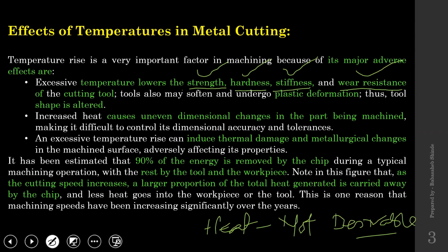But when there is increase in temperature beyond a certain limit, this temperature increase is going to have a negative effect on all these properties. So strength might decrease, hardness might decrease, stiffness might fall by some value, wear resistance also might fall, right? So all these things might happen with a cutting tool, and that way it is completely undesirable.